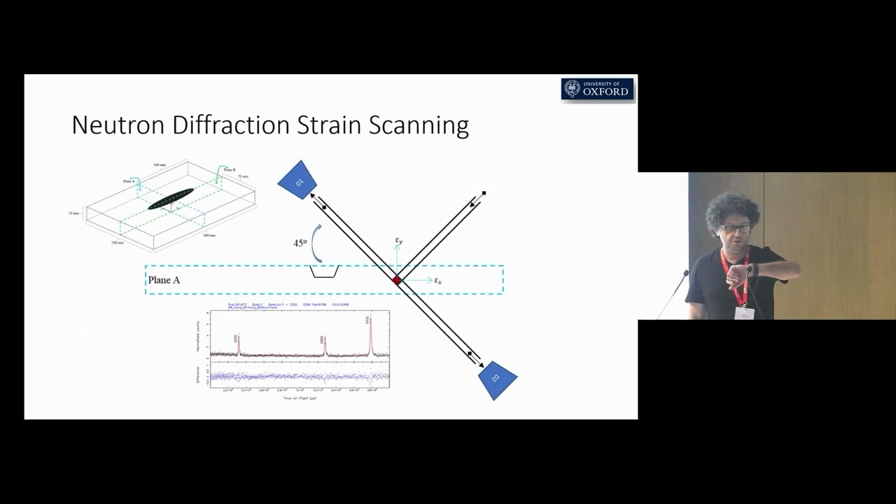Okay, now I will show you a neutron diffraction experimental validation. For this validation, we measured 2 components of residual elastic strains, X and Y, but I want to remind again, we have experimental data for the Z component of displacements. So this is a challenging condition. We are challenging the model to quantify stresses different than the component of experimental data.